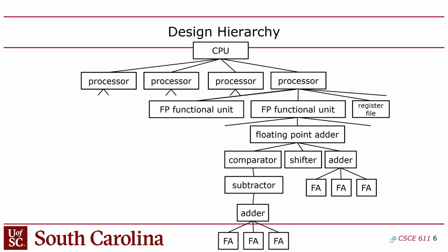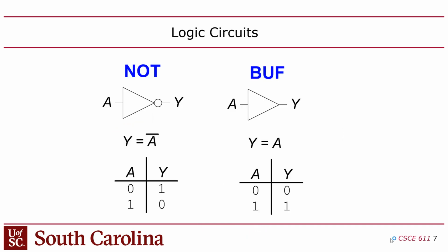Now you might say, what's the deal with this hierarchy? Why is this so important? Well, when you read a SystemVerilog file, the first thing in that file is the word module. Every file is a module. Most code that you write in SystemVerilog is going to be structural code where you're taking modules and connecting them with wires, essentially. So everything is a module in Verilog. It's an important concept, not only to understand, but to try to leverage.